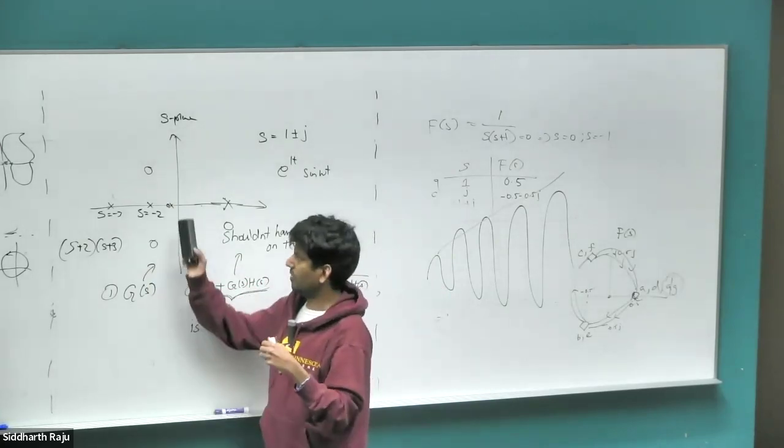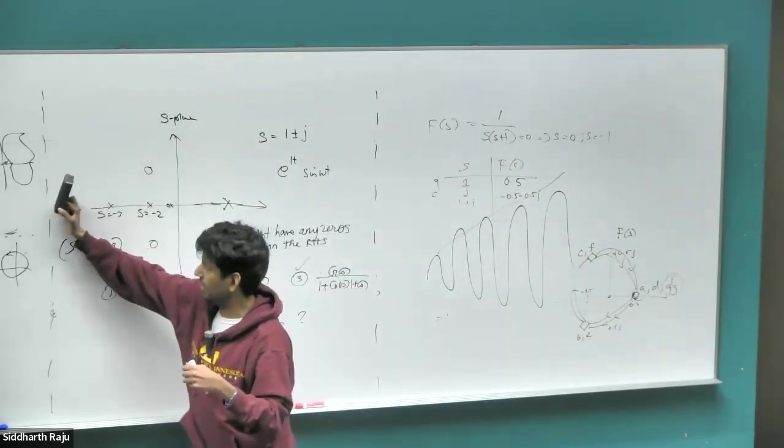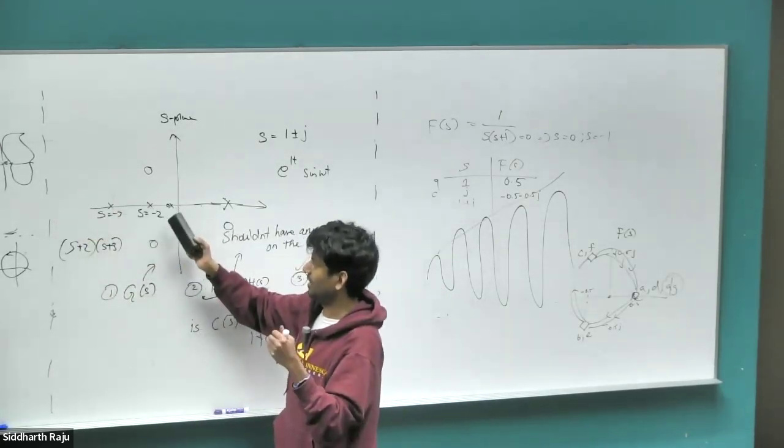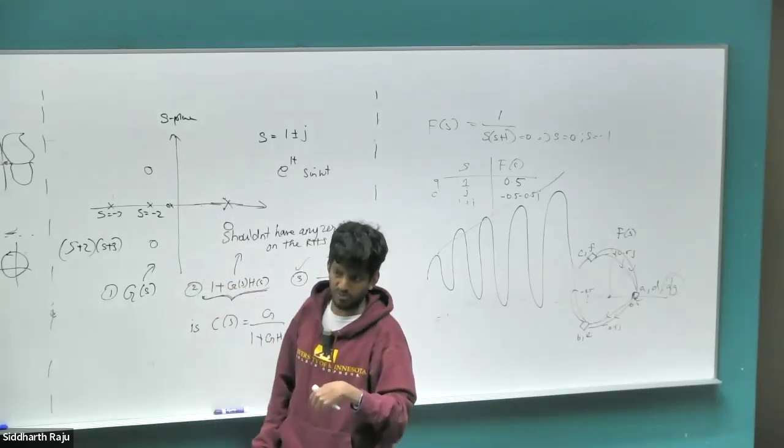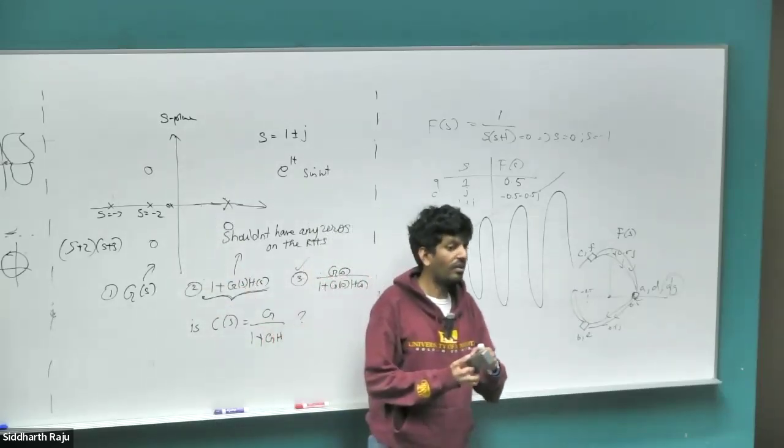You want a better phase performance, so you want to put all the poles far away. So the only thing you can do here is use a lead lag compensator and cancel out the poles very close to the y-axis.